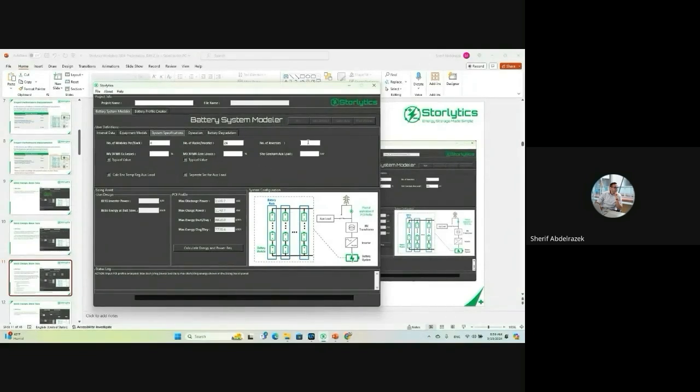Right? So for the number of inverters here, we'll select 1. And as we're filling out these numbers, you'll notice the design capacity is updated. So now I see that for the system we've designed, total inverter capacity is 1.1 megawatt, and battery energy capacity at battery terminals is 4.8 megawatt hours. For medium voltage transformer losses, both copper and core losses, we can just use the typical values, which is 1% and 0.1%.